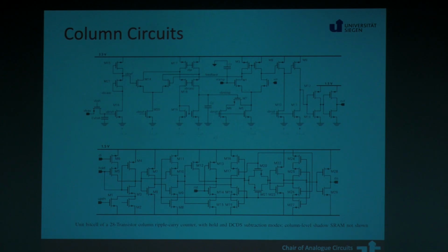If you look deeper into it, I'm not going to explain this to you, but what you can see is that's my sample and hold. There is a switch, there is a capacitor to hold. This is my comparator circuit. You can see there is a kind of differential amplifier here. There is a cascode circuit which has come here. These are current mirrors. There is a golden cascode. So it's a two-stage comparator. It's not a tricky design.